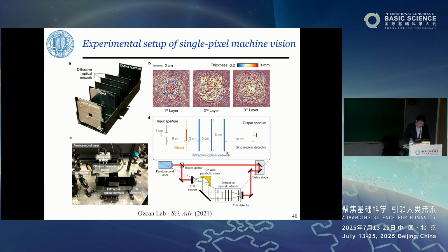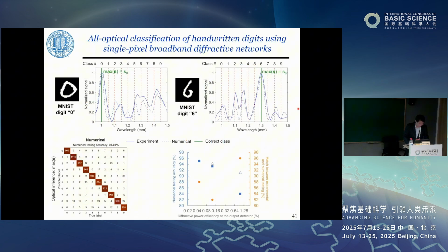So these are the experimental results of the 3D-printed class-specific diffractive camera, validating its capability to selectively image only objects from the predefined class. In each block, the top row displays the input test image followed by the corresponding numerical simulations and experimental output images obtained using the terahertz detector. For the target class, in this instance the digit 2, both the simulations and experimental results exhibit clear image formation, confirming that the camera successfully reconstructs the desired object.